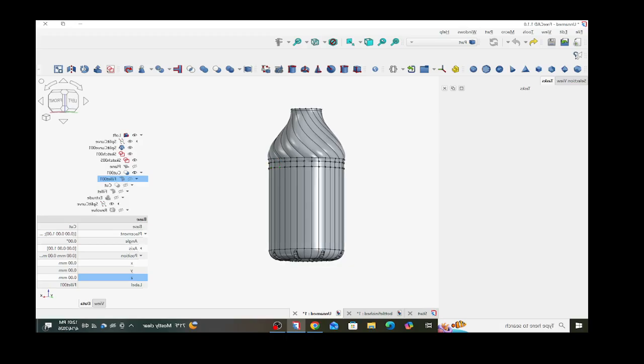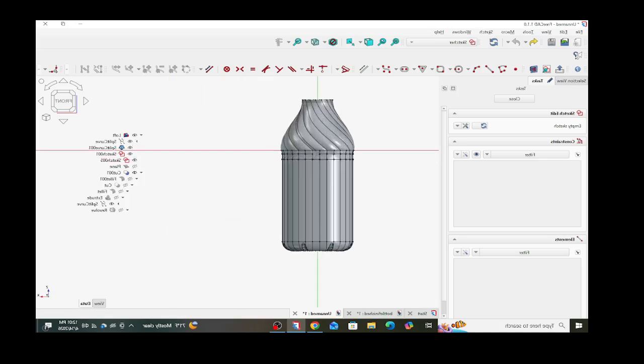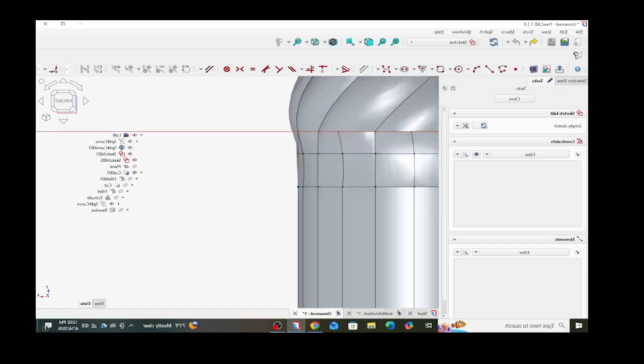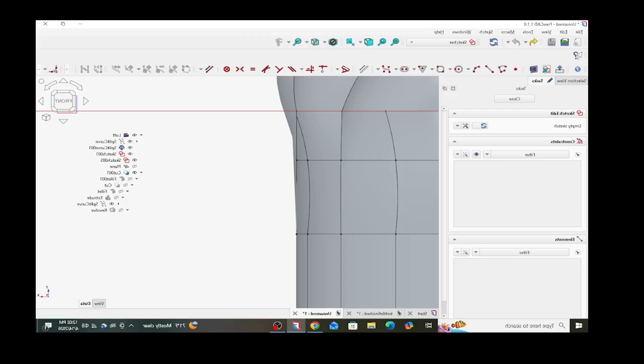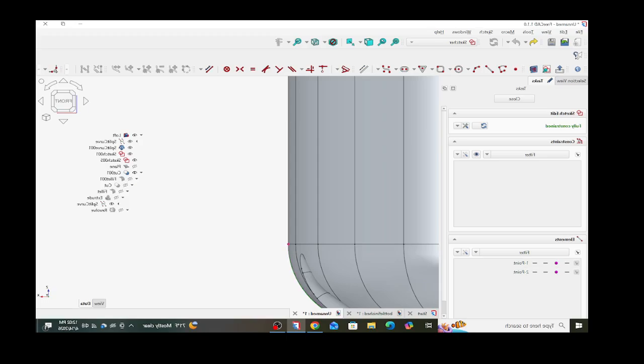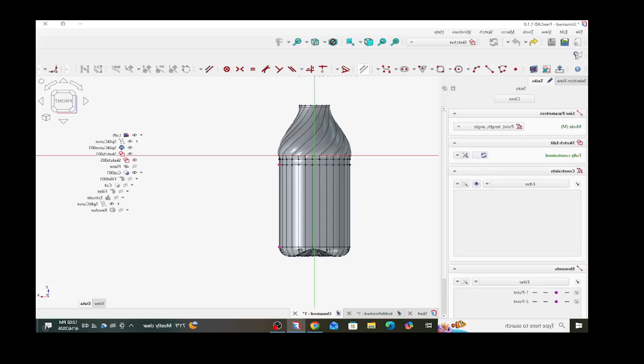Now for the, click off in the front view, I'm going to create a new sketch. We're going to view the section. Now this is not quite tricky, but we're going to bring out this point and this point right here. We're going to make 7 ribs going around the bottle itself. I'm going to snap a construction line between those 2.